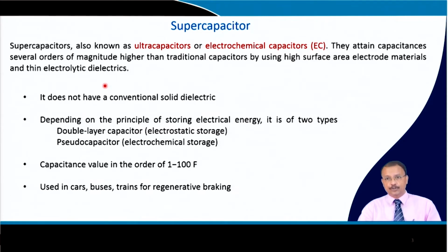Initially, I introduced the supercapacitor in a gist form in my first module, lecture number 3, where we talked about supercapacitors. So, there you have gotten the idea of what I mean by high surface area electrode materials and also thin electrolytic dielectrics. So, it is the charge separation at the surface of the electrode. So, the value of D is very small and the value of A is very large. So, they constitute what we call this ultra capacitor.